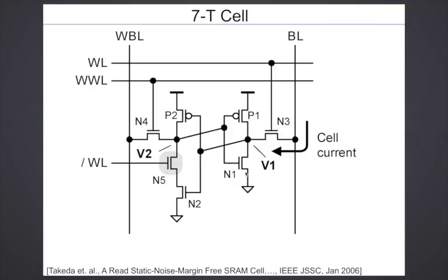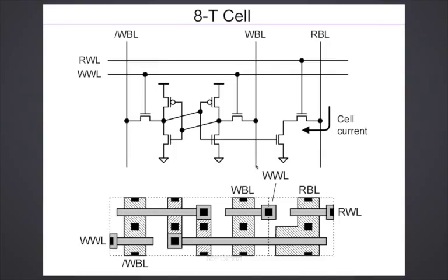And the answer is, you don't have to stick to that rule anymore, because now even if this goes up, you have made this SNM free, right? So I can actually have these be equal sizes, so you can take advantage of that to reduce the size if you want. Same for the read buffer case also. And if you see out here, they are the same size. The widths of the NMOS and PMOS are the same. I'm sorry, the NMOS of the driver and the access are the same.